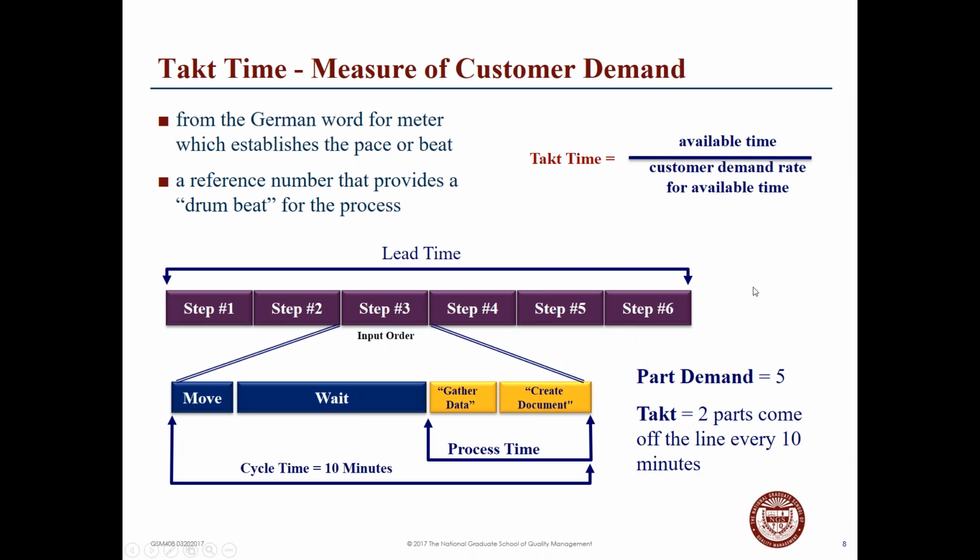to be able to determine how many parts are going to come off the line. So if your customer wants to get 15 parts per hour, if this is an hourly rate, that would tell you you've got to have 3 production lines, because you're going to get 5 off each line. And so if you wanted 15, you'd have to have 3 lines. And so that's one of the things we use takt time for, is to help us decide throughput and whether or not we have enough production lines to meet the needs of the client.